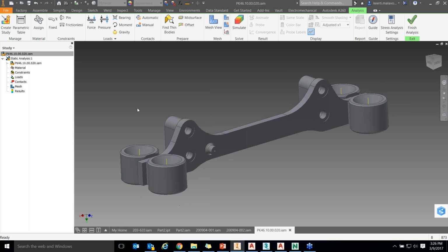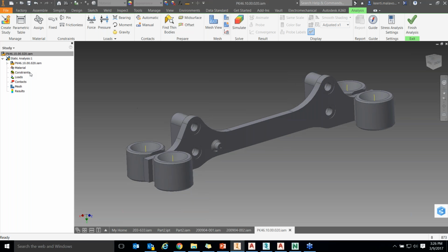And it is very simple to use, where you just have to follow the things which are available in the model tree, right click, and I say show all materials. So it automatically recognizes the materials that have been provided during my design stage itself. So it's made of steel, mild steel and welded mild steel.